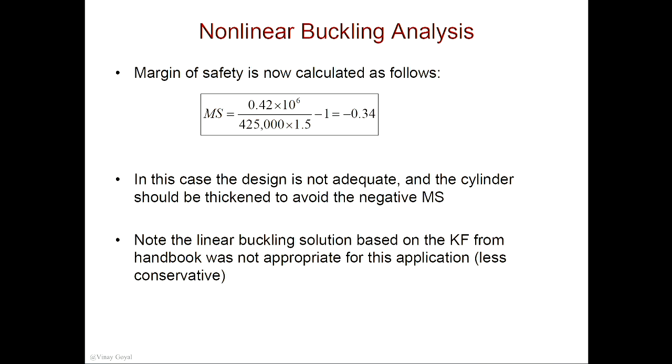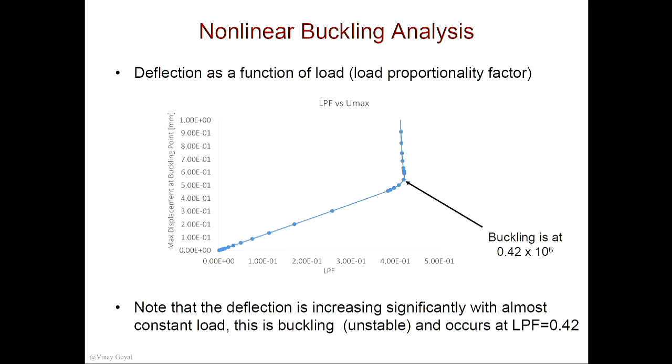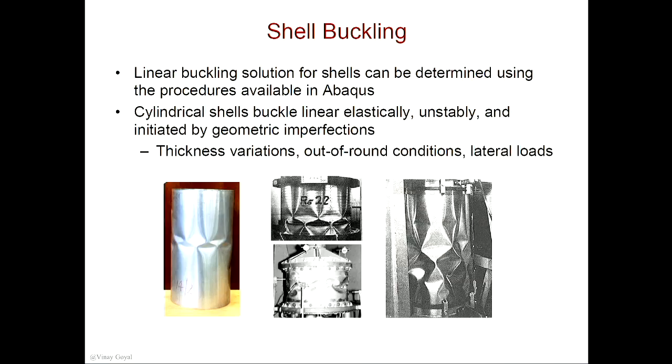Why do you call it linear compared to nonlinear? What is linear compared to nonlinear? You mean the approximation function, or what? When you're saying linear buckling? So linear is using the strain displacement relationships, right? Yes. But it is a linear analysis. It's using nonlinear strains, but it's linearizing the equations, right? The stiffness equations, because they're nonlinear in nature for large deflections. You're linearizing that, and then you're finding the eigenvalues about the zero state, the perturbation state, which is zero state. Remember, when we go back to the beam problem, what is the trivial solution there?